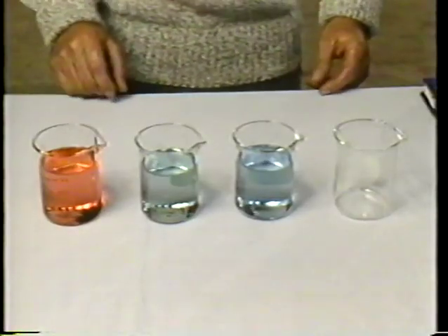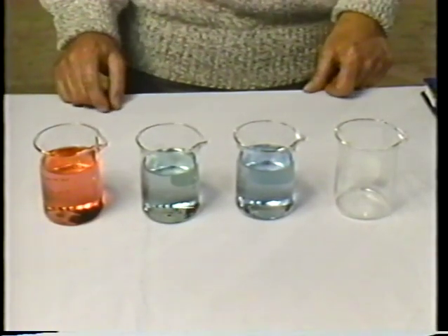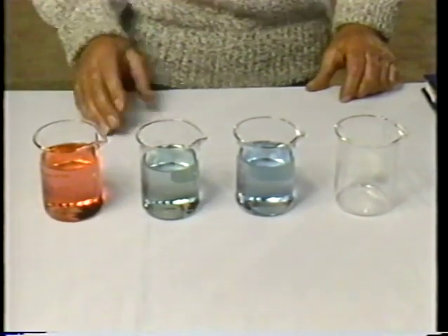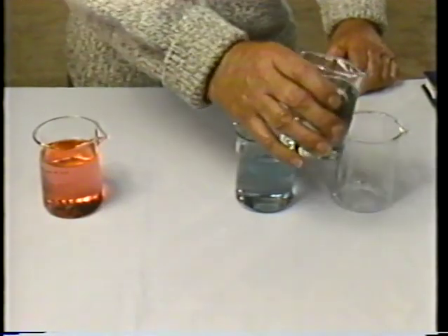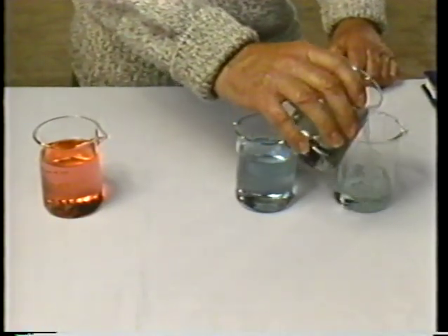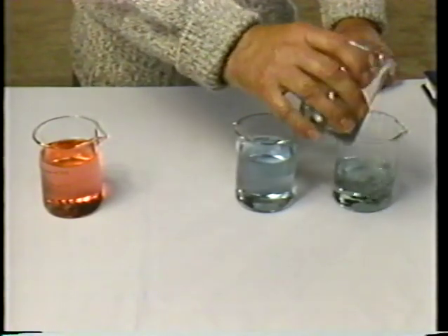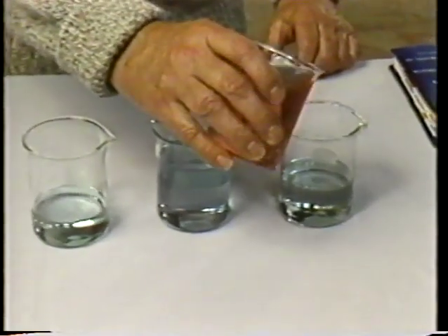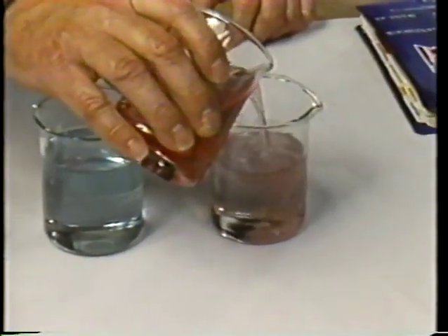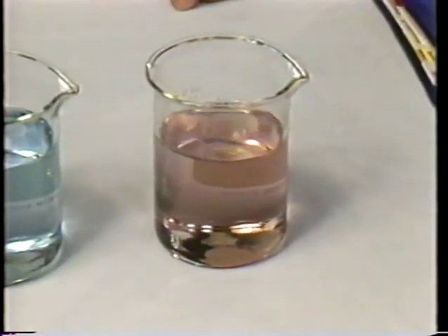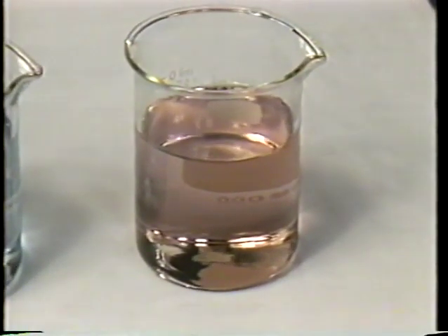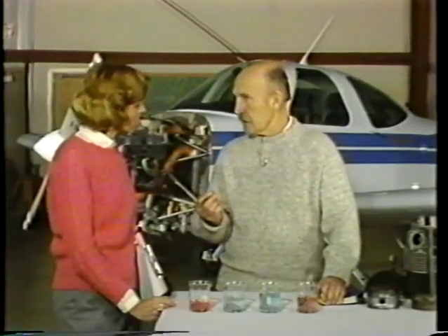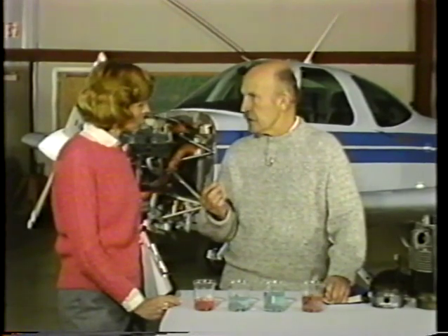How do we know if the fuels have been mixed? Well, when the dye is put into the fuel, this dye is such that if we mix the fuels, and I'll show you how that works, the color will change. The color tends to disappear, and the liquid fuel then should go from, say, a clear to a straw color. And so when you take your fuel sample, if it's clear or just slightly yellowish,